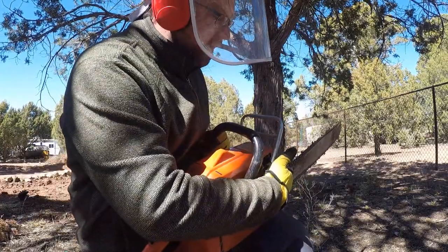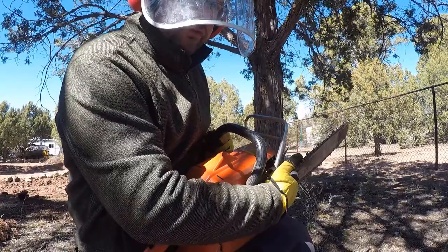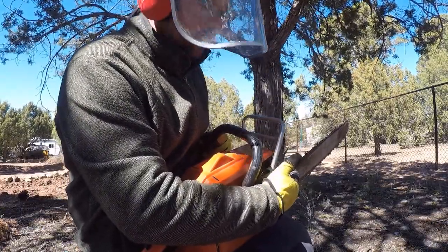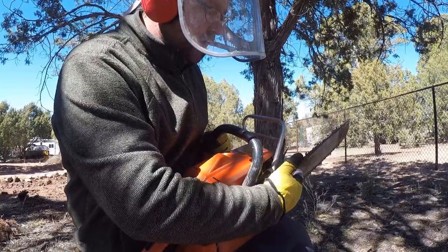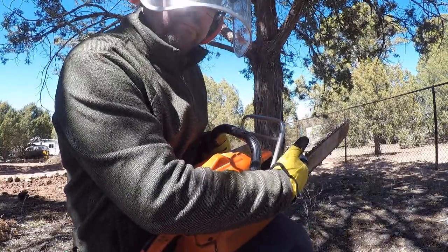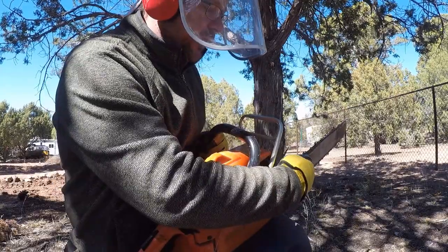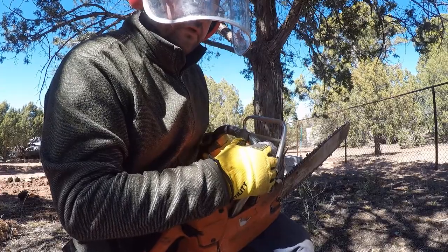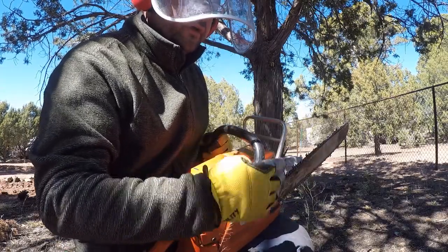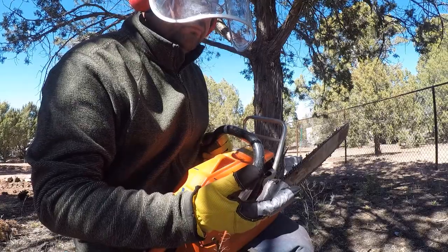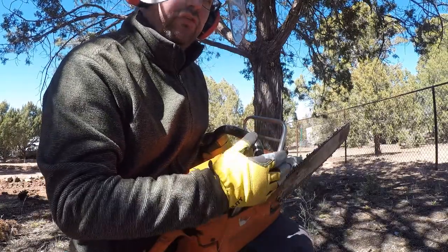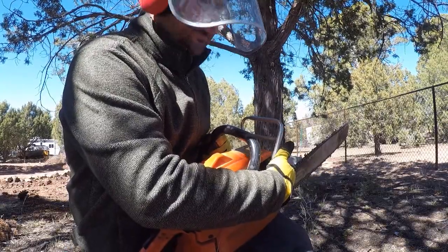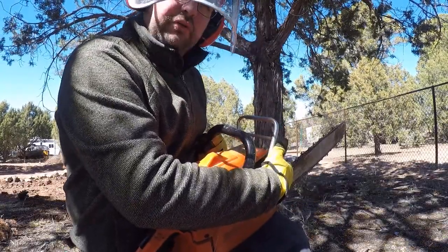The other thing I see a lot of people do when using a chainsaw is not realize that a chainsaw should not be kicking out sawdust. If it's sharp, it should be kicking out a more coarse material, what's called saw shavings, not sawdust. If your chainsaw is kicking out sawdust, it means you need to sharpen your chainsaw.